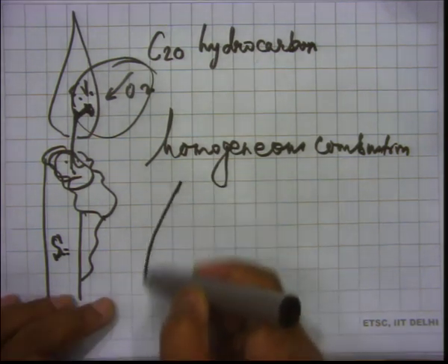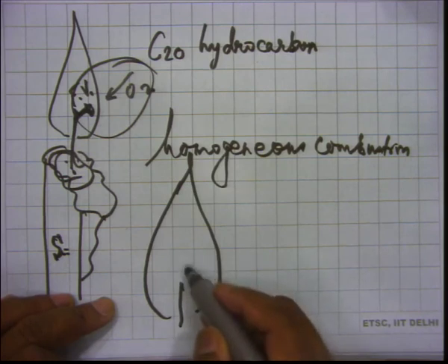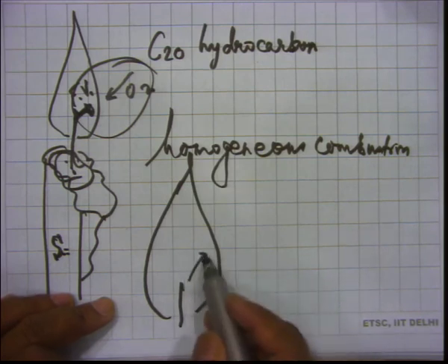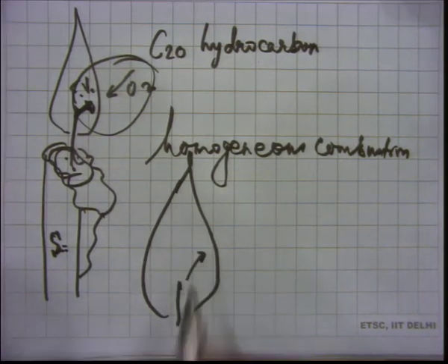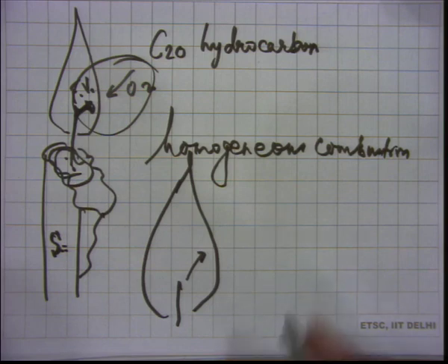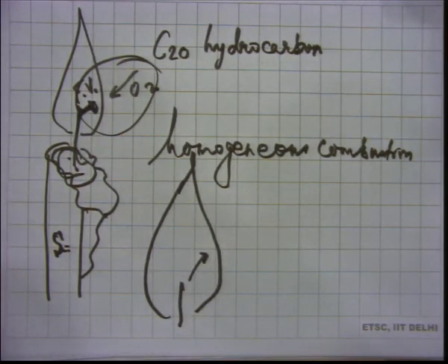But think about it, when we have this flame here, we also know that the fuel vapor, when it goes towards the flame, on its way it keeps thermally breaking down, and actually something starts happening. It produces polycyclic aromatic hydrocarbons, and then some of them react in complex fashion to give you finally soot.